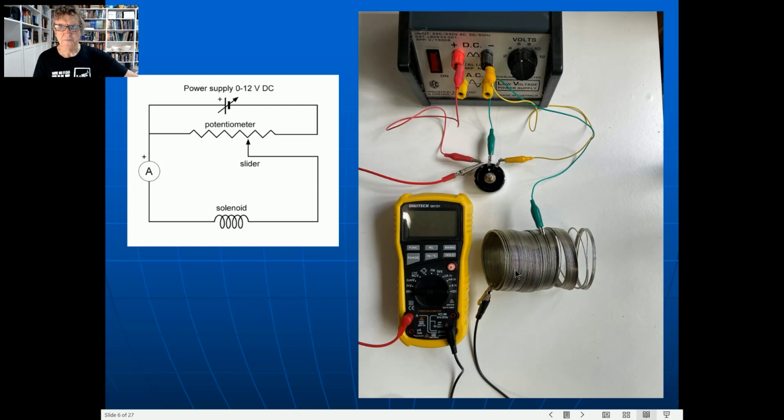Then the current goes through the slinky, out the green wire, back to the center peg or center terminal of the rheostat. Okay, so that enables me to change the current through the slinky, and that'll appear as 2 amps on the scale when we see it going. And then of course you have the other terminal going all the way back to the negative terminal of your power supply. So that's the setup, pretty simple.